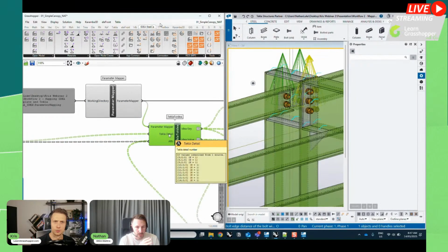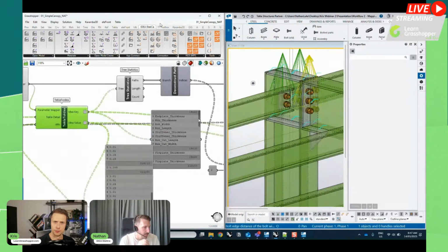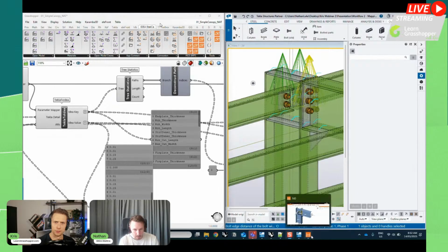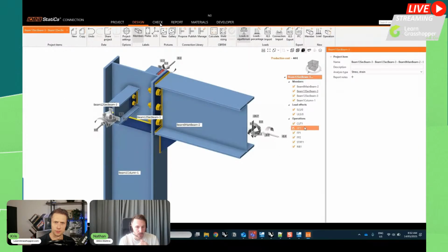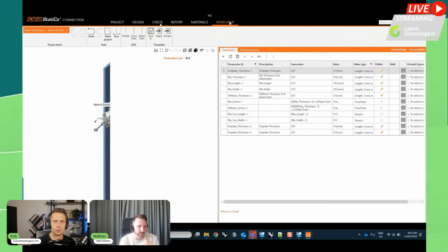So it will convert the length from Tekla, which uses millimeters, to IdeaStatica, which uses basic SI units. So you can see here, once I pass it through that Tekla to idea component, the attributes we input get converted to the idea parameters, which that is linked to.